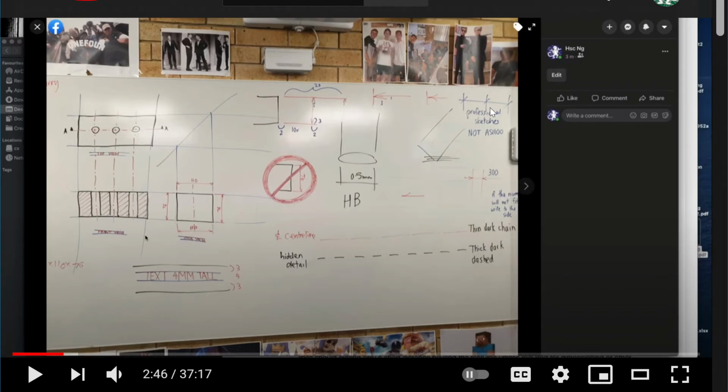I will say that professional engineers draw their lines up in this top corner. You can see this blue line, and they just draw the line across, and then they draw a 45-degree line at each of the intersections. That's how professional engineers do it. I tend to do that because it's very, very fast, and as long as people know what you're doing, it's a reasonable convention. If you can't fit the dimension inside the dimension lines, you can draw the dimension outside the line, which is what's going on in this corner here.